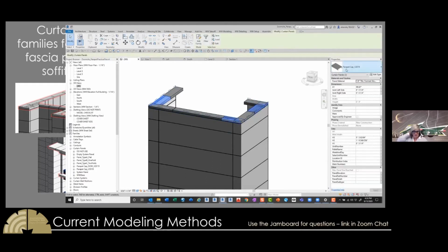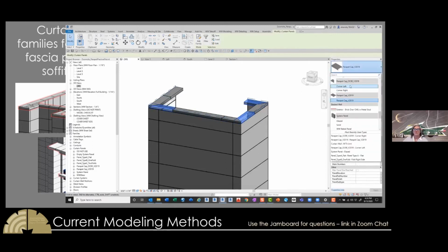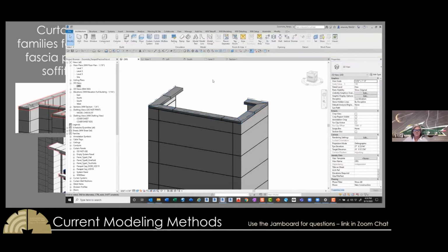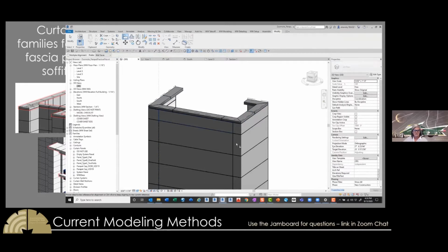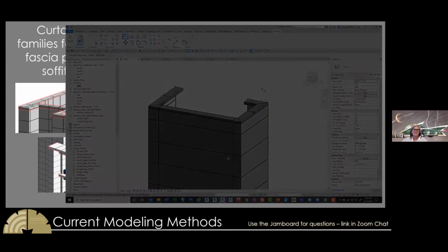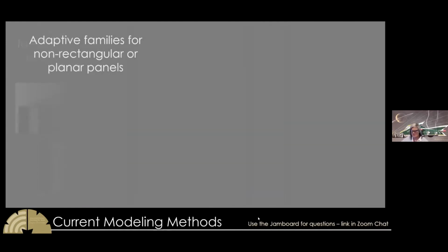Gabe has a good trick for making some mitered parts that we're going to probably incorporate into these families so we have fewer families. So, but for now we have a left and a right outside 90. So I just switched those out. And you can edit those families and change the miters. And the last thing I'm doing there is just aligning those joints. Of course, that last little panel is really tiny. Okay, it's not necessarily realistic.